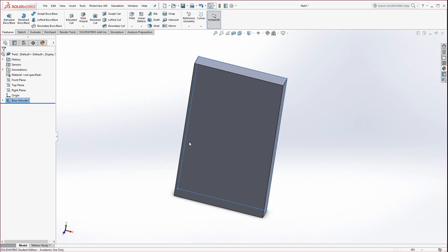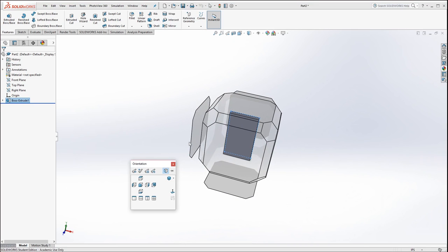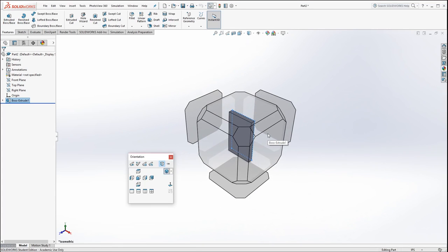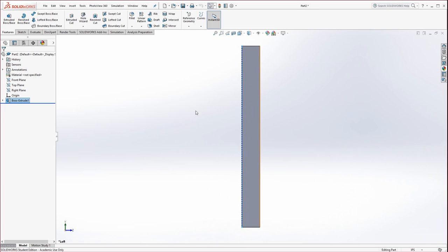Now here's the great fast key, the space bar. Hit your space bar right there in the center between the Alt keys. And with that, you'll see a cube come up. If you don't see the cube, this orientation dialog box appears. Make sure that your view selector appears. I just call it the cube because it looks like an ice cube. With that on, it's very nice because you could select different view states. Like if I click on this corner, it'll go to an isometric view. Hit the space bar again, you could select, I want to see the left-hand view. That's this little plate on the left. Click on that. It'll orient you to the left side.